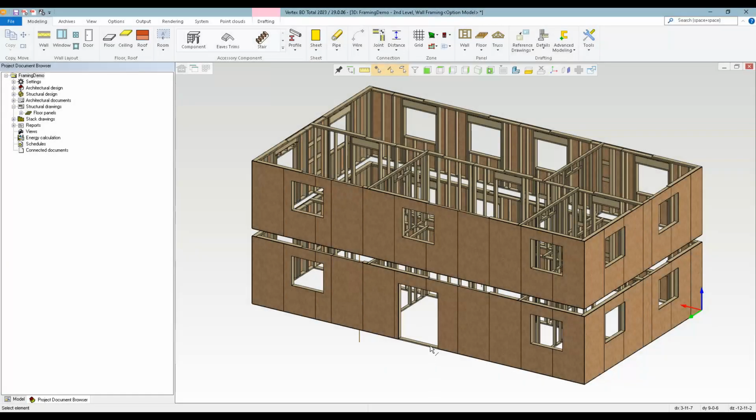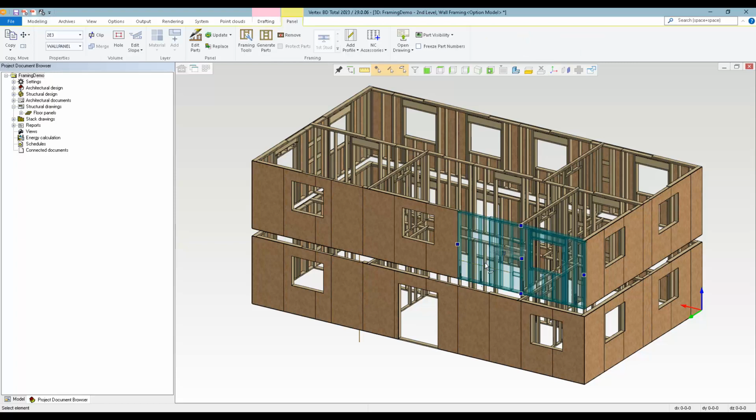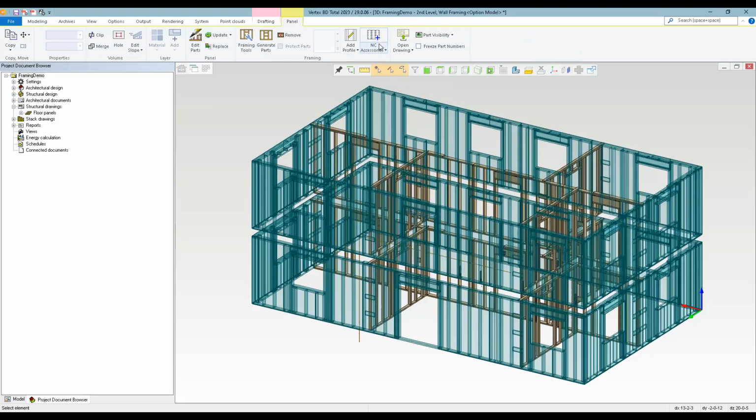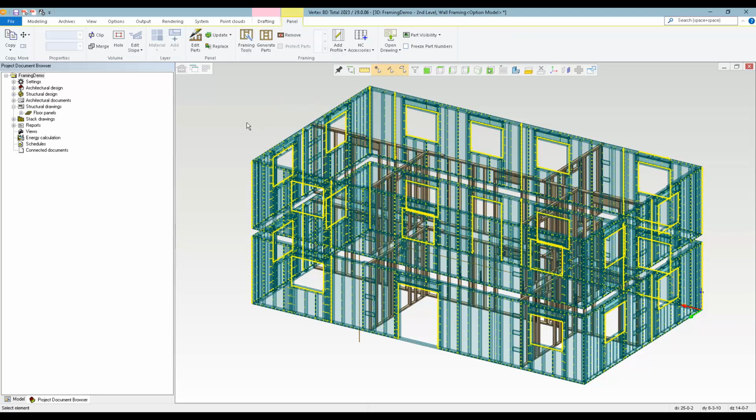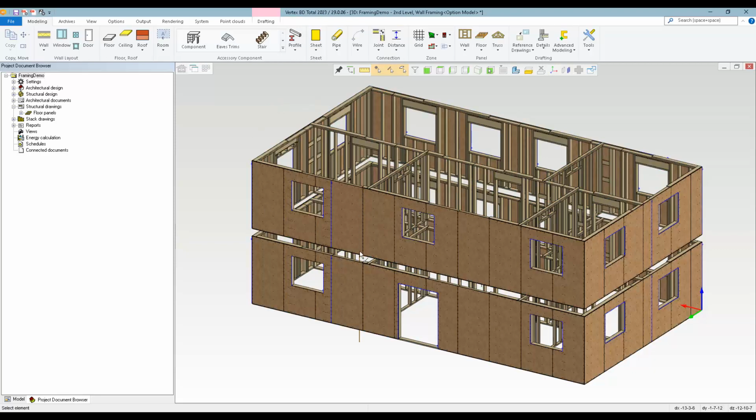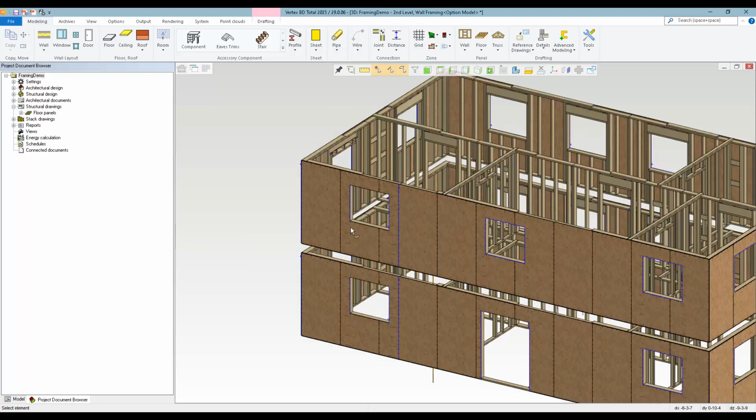If you have a wall panel line in your factory with automated nailing bridges and routing, you can generate that information in Vertex as well. I'll select all my wall panels and then run the NC Accessories function. This function can be set up with different rules for nail patterns, whether it's along sheathing seams, the edges, and within the sheet. Notice it also created these blue lines. These are the routing lines where the sheets need to be cut. We can also add glue lines as well.